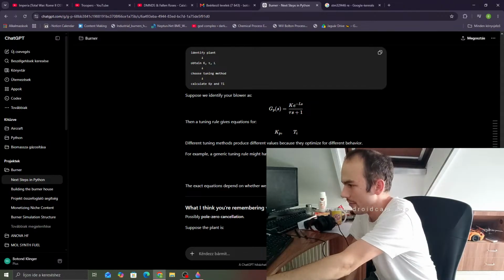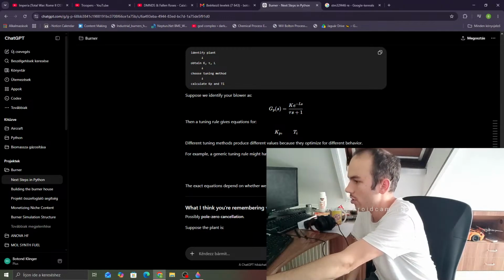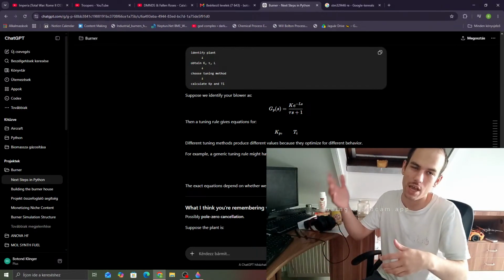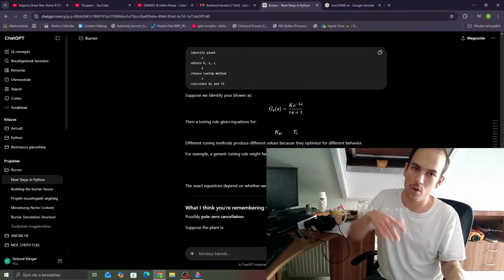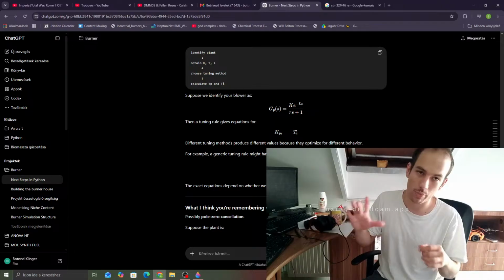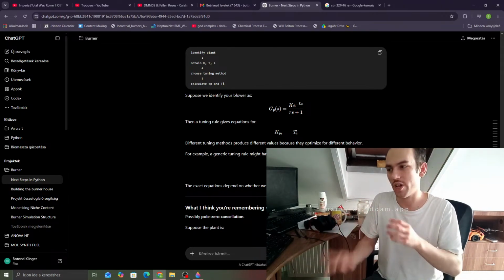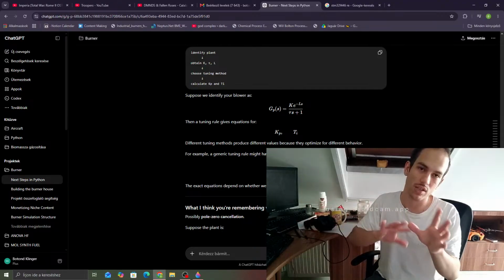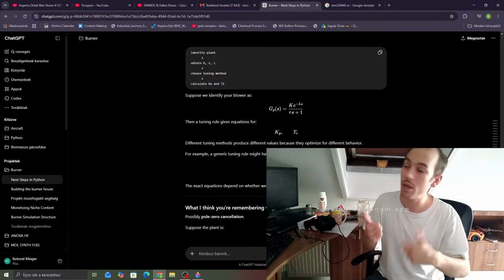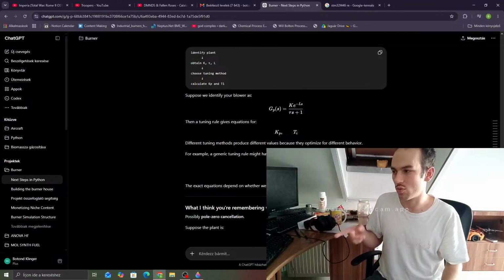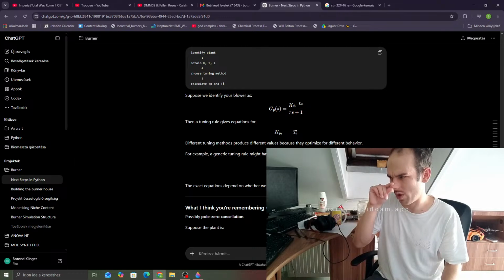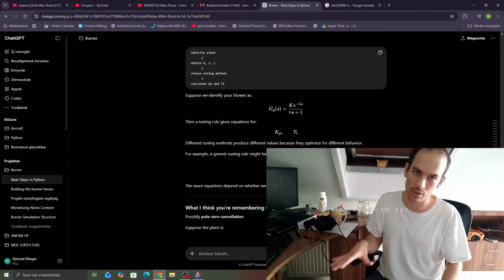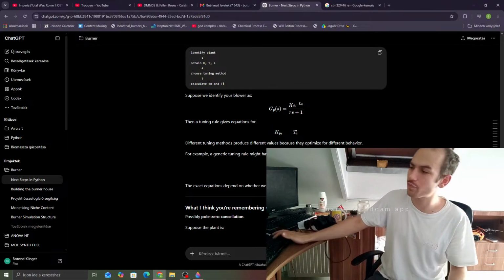I haven't even heard of these, to be honest. I have heard of the Cohen-Coon and the Ziegler-Nichols. There are a lot of tuning styles. We can use MATLAB, which has this thing called PID tuning, and it finds these constants and all this kind of stuff, so it's pretty fun. I think it uses Ziegler-Nichols or Cohen-Coon, I can't remember. The point is, it finds you good values, but we will do it without that as well.